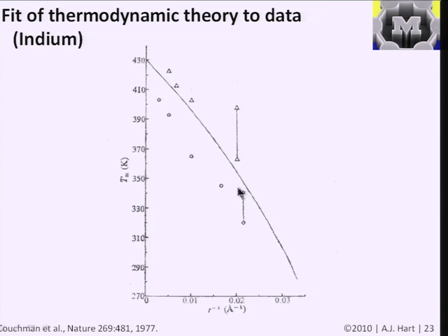So it says that a 5 nanometer particle of indium is going to melt at, say, 80 Kelvin beneath the bulk melting point, which is about a suppression of 20%. So it's a non-negligible decrease in the melting point, and is a much bigger decrease than, for example, we saw in the lattice spacing due to the internal pressure inside the solid.